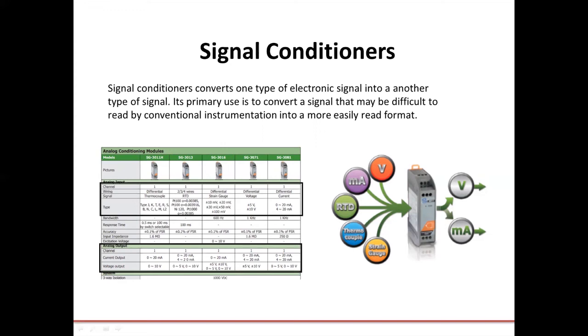This will save you some money theoretically and save on hardware too, because as opposed to purchasing an extra module for thermocouple input or a module which has the ability to do a thermocouple, you can just purchase one that does voltage or milliamps and oftentimes save money, hardware space and wiring. We have various signal conditioners to convert most of the common signals, but these are traditionally just used for converting one sensor type to another common type.